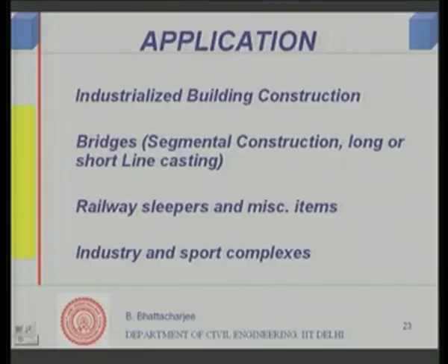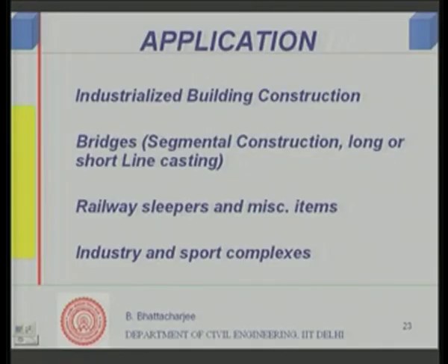I know the Allahabad bridge over the Ganga is a recent bridge, which is long line casting. Short line casting has been used in many. The Ganga bridge in Patna is one of them. Many Delhi flyovers are segmental construction of this kind. Railway sleepers have been used for many years, and many other miscellaneous items. Industries and sports complexes. So, these are the possible applications of the precast industry.